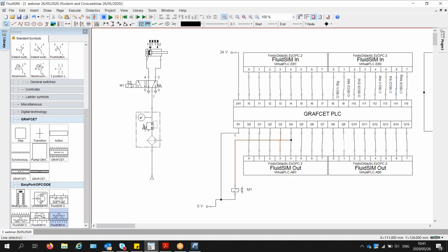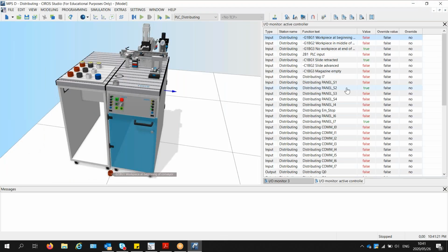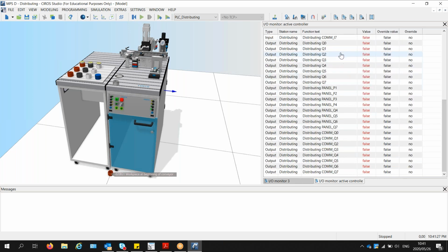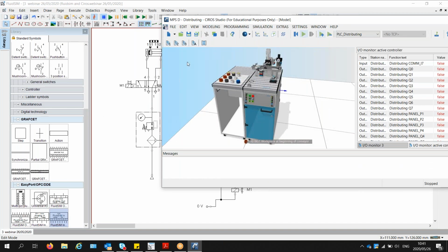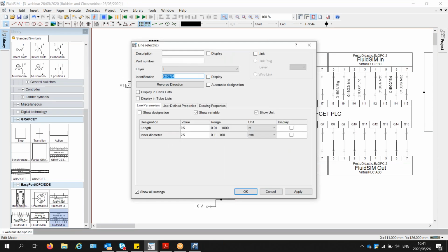Now we're going to go to the outputs. The outputs are not indicated like the inputs. This is because this is educational software, so it is expected for the students to study the system, to turn on individual outputs to identify what happens, because that's part of learning. But because I know, to save time, I'm just going to quickly label this. This is M1, to eject workpiece out of the conveyor.